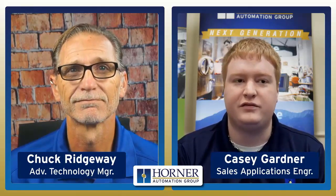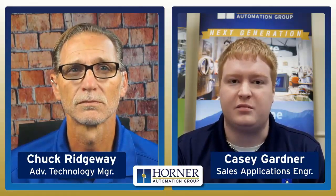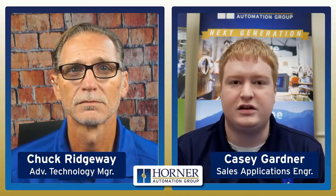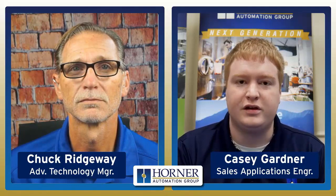It's going well. And we were talking before the show, and you mentioned that you were just helping a customer today with this very feature. Yeah, absolutely. It's a common application for sure. We had a customer looking to integrate us with a SCADA package, so Modbus TCP Slave, very easy configuration and just a little bit of info on the Modbus table, and they're good to go.